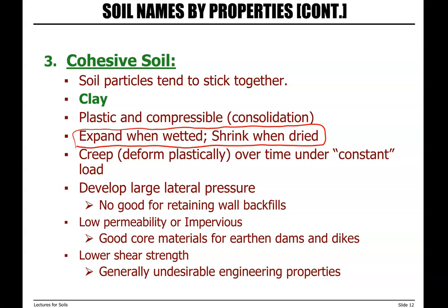So we will have cycles of expansion and shrinkage, and this can cause stress in our structure. Another characteristic is that there will be creep in clay, which is deformation over time under constant load. In materials, when we increase load, we will see an increase in deformation. But creep is when the load is constant, but with a constant load, we still see an increase in deformation. That is referred to as creep, and that's something that we see in clay.